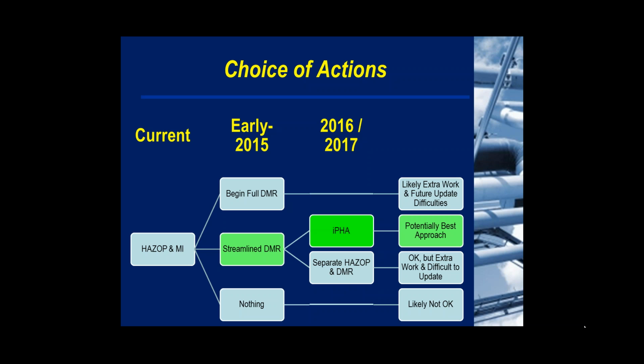The objective is controlling the hazard and reviewing the gathered information, evaluating it and verifying that the metallurgy and materials are compatible with the process, the equipment is currently fit for service, you really don't have any credible potential for degradation between the times that you're performing inspections and evaluations, and that your testing and inspection program and procedures are adequate. These are things right now that you know you're going to have to do as part of any damage mechanism review and as part of any thorough mechanical integrity program.